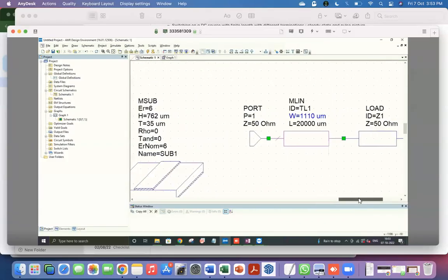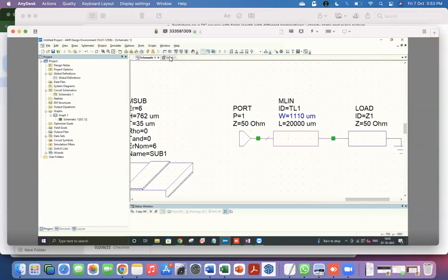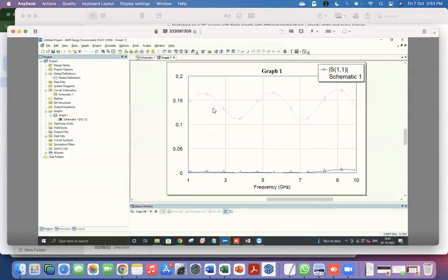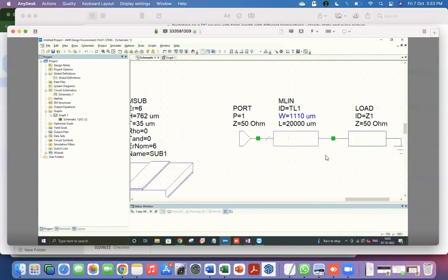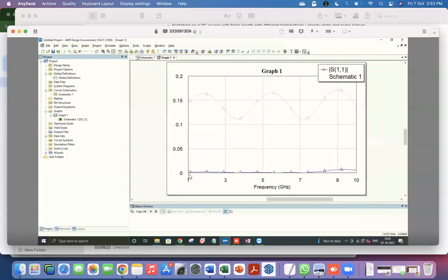So yeah, and another point is that if you're trying to use these kind of techniques to figure out, it's important that you keep the length at least several wavelengths over the range of frequency you're interested in, because otherwise you can actually be fooled if you look at a very narrow range of frequencies, because you will not know whether you are mismatched, especially if you use very low frequency numbers, because at very low frequencies, the transmission line is essentially non-existent.